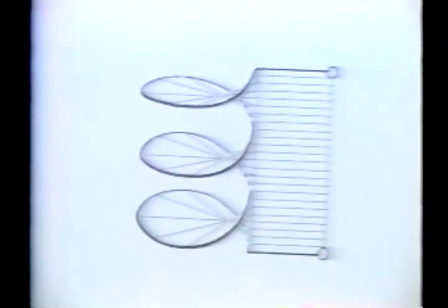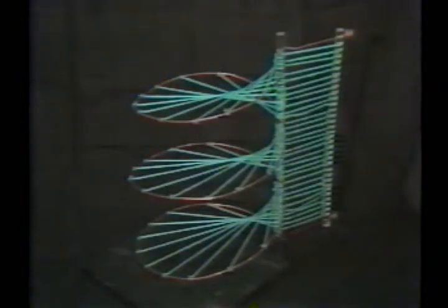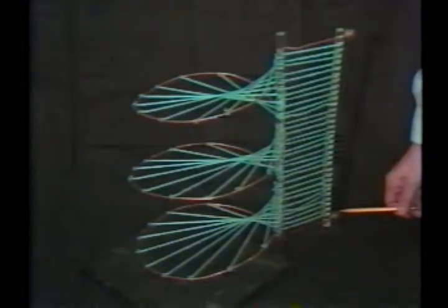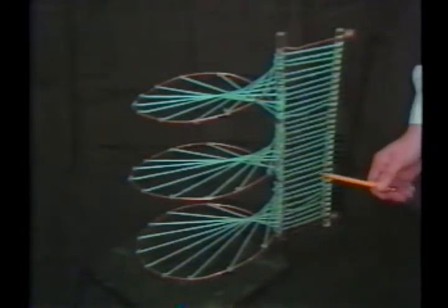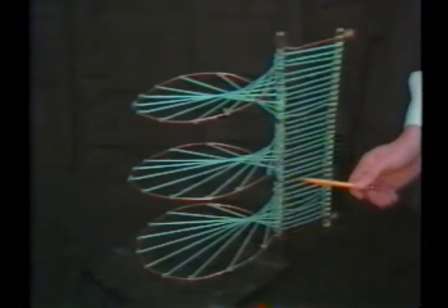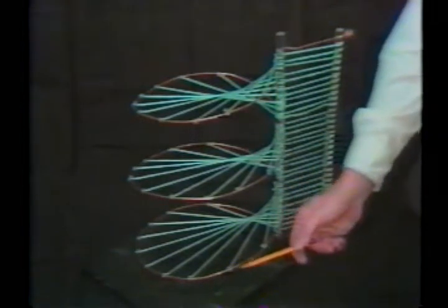In evaluating Faraday's law, the contour goes from the terminal at A to that of B along the coil wire and closes through a path outside the coil. However, the electric field E is 0 along the perfectly conducting wire. Hence, the entire contribution to the line integral comes from the path between the terminals from B to A. Thus, the circulation of electric field E around the closed contour is just the negative of the terminal voltage of terminal A with respect to B.